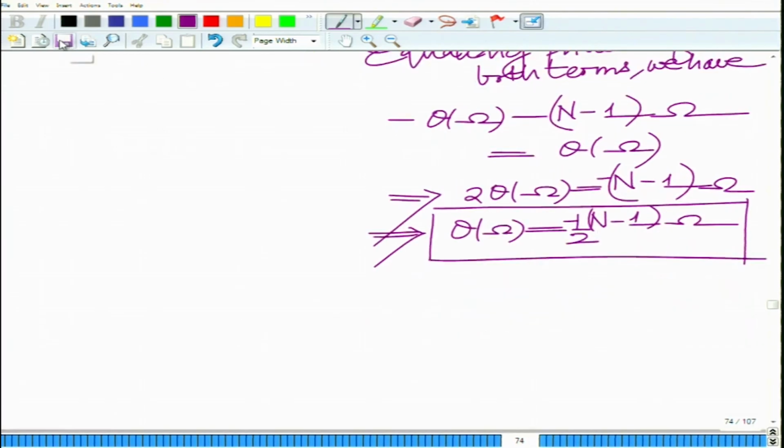This basically satisfies a linear phase constraint. So, this is a linear phase. Phase is linear with omega. So, this has the interesting property that by this symmetry, the symmetric property of this real filter results in a linear phase. In fact, that is something that is very interesting. So, the symmetry property endows it with a linear phase.